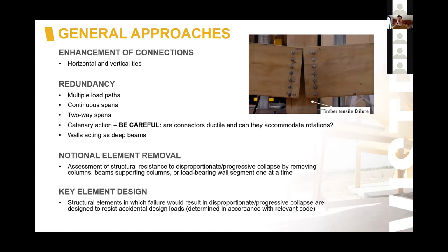You could start with a qualitative approach and, just by inspection, make an assessment of the structure and look at if you were to remove certain elements, would that ensure that you've got a robust design? And then, if you believe that you can accommodate that, you might move into some finite element analysis and things like that to do the final calculations.